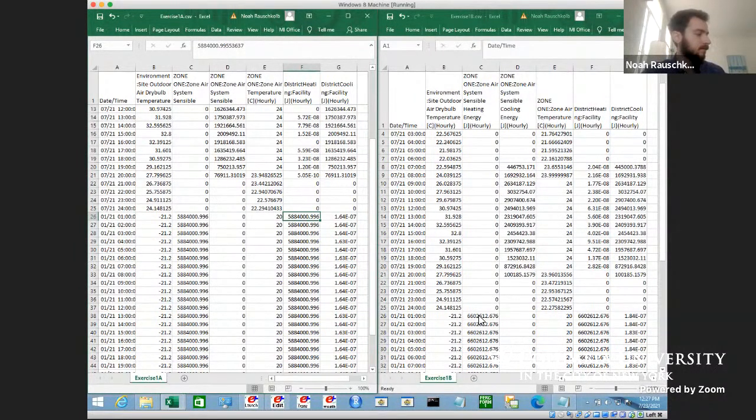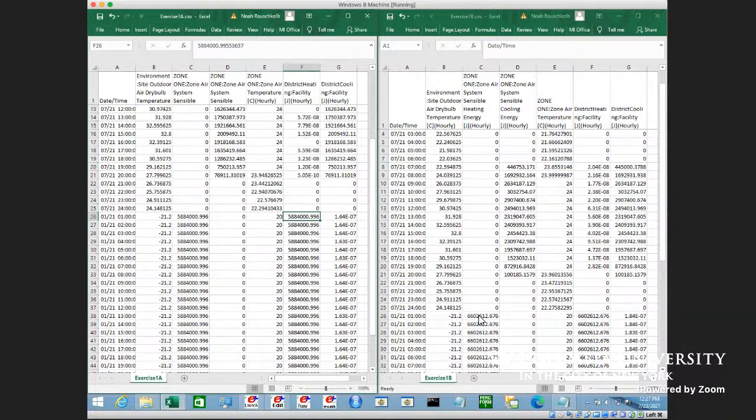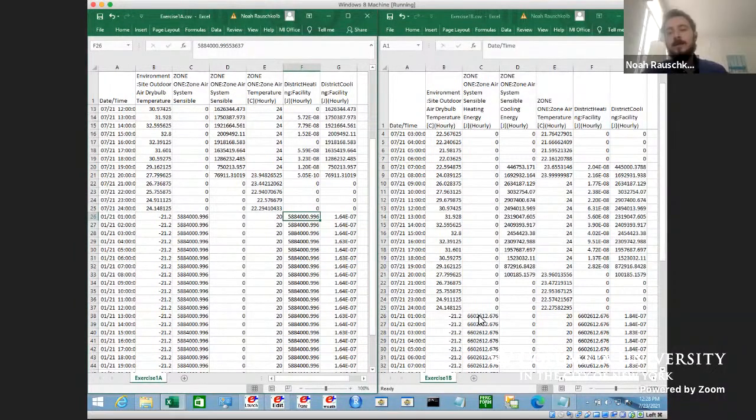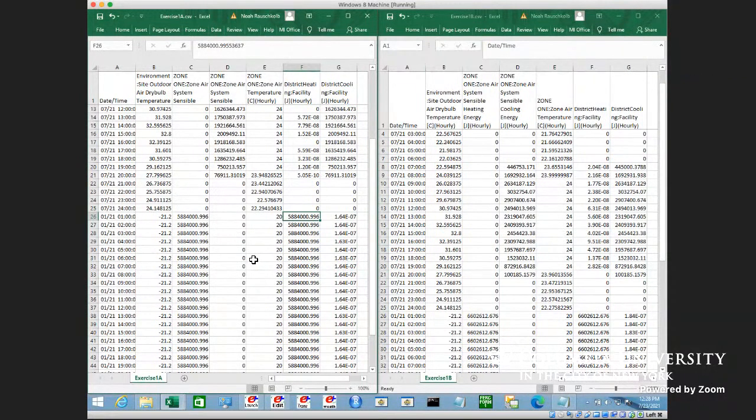500 square feet. And why is it that hourly it remains exactly the same? You've got to go back and watch the YouTube. We're recording this, but the standard for doing these design days is you do a steady state calculation for your winter design day, and you do a transient calculation for your summer design day.